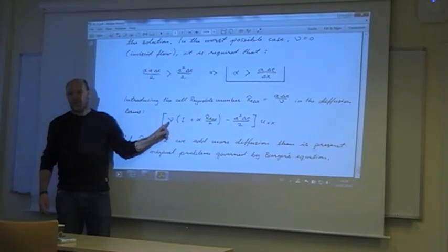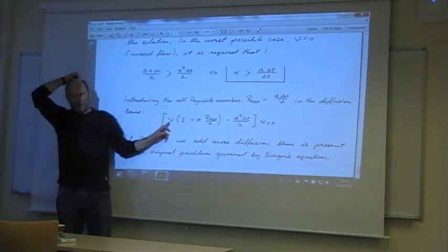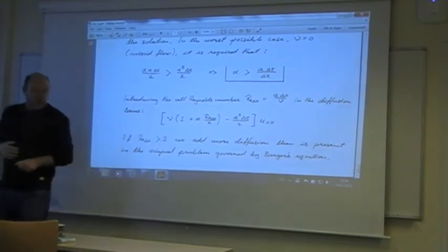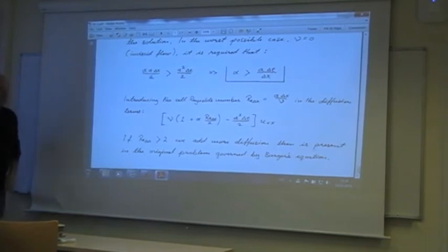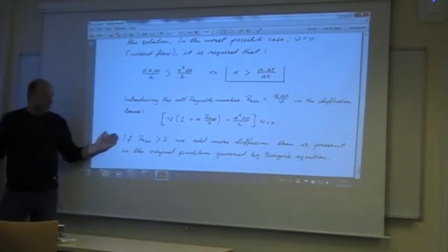So if you think you're simulating air, you're not. You're simulating honey or something, very sticky fluid. So it's dangerous using this upwind scheme, of course it is. So that's something we have to keep in mind. It will be the discussion next week.